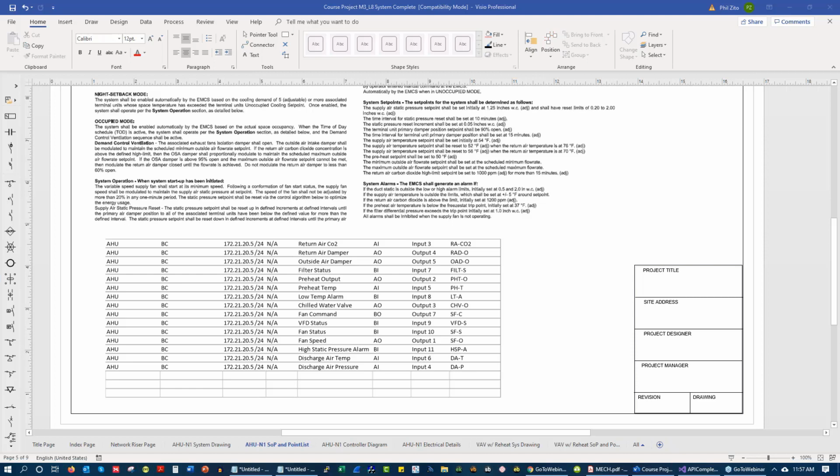But if you've got 2 temperature sensors and you're not 100% sure where they should be installed, it's okay to field verify that. When I look at details, I look at mass and impact. If there's going to be a massive amount of something, I want to verify that that's accurate. Who's installing it? What part number is it? Etc. But if it's something minor, a couple things here or there, a graphic, stuff that can be easily fixed, then I'm not going to spend a whole ton of time going through an RFI process on that.